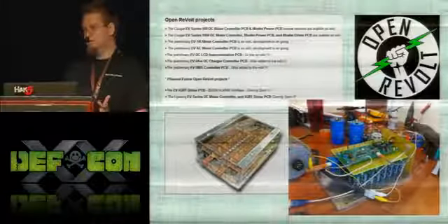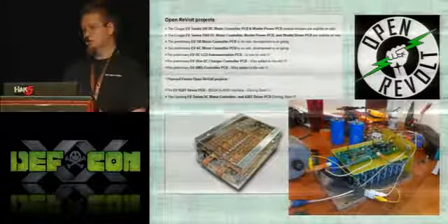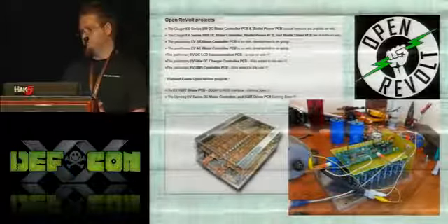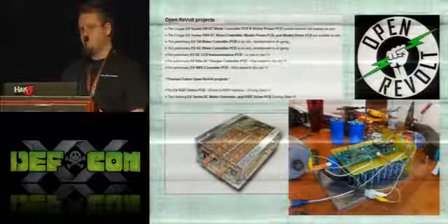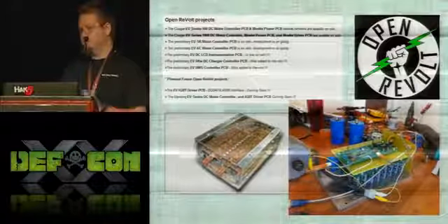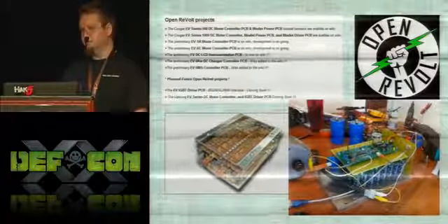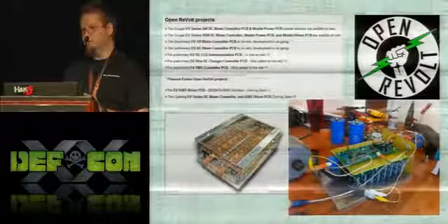So with my car, I have a 120-volt charger. I have a 120-volt controller. If I want to upgrade to 144 volts, I have to replace both of those. And with the do-it-yourself, you can just change a couple lines of code and you're running at something different as long as your components can handle it. So it's real easy to upgrade it within a certain range.